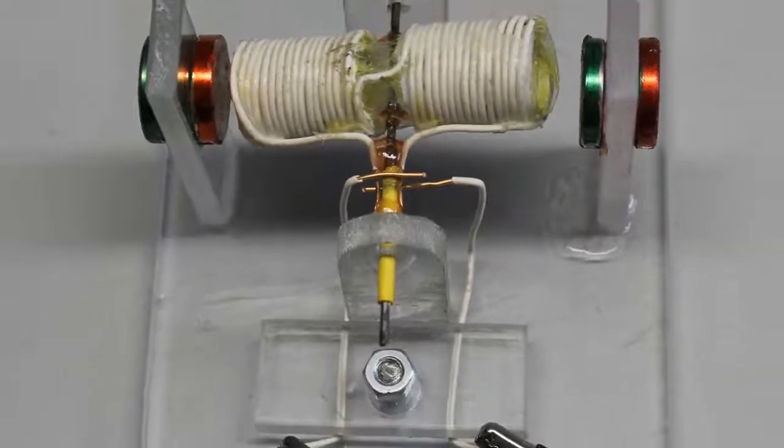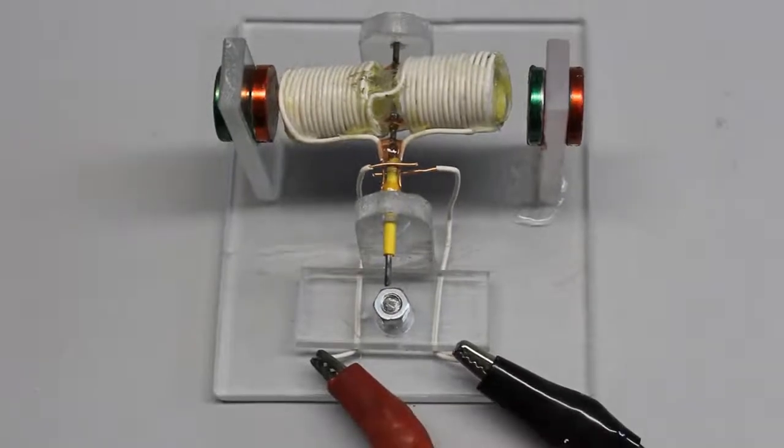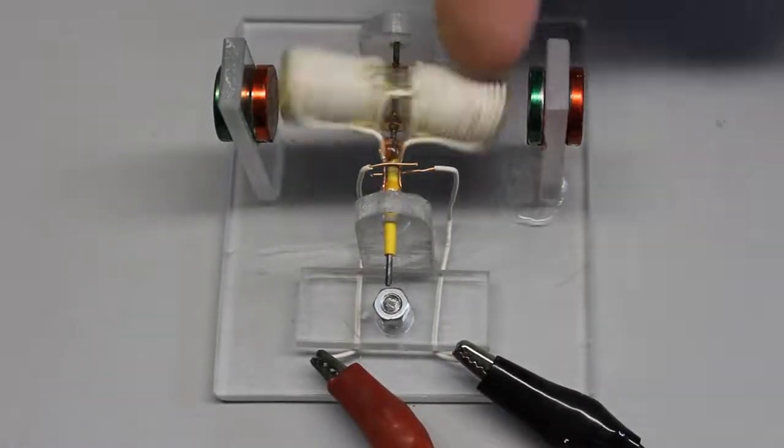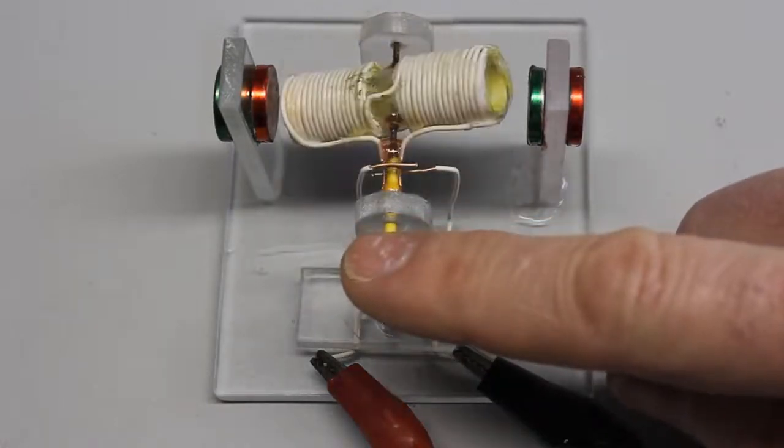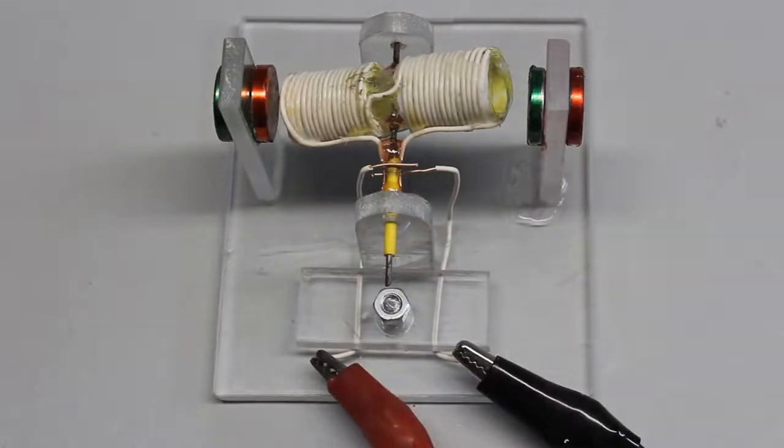The real electric motor also starts spinning after pushing it slightly to make a first contact with the commutator. That need for an initial push is a disadvantage of that simple motor. Another one is that the motor stops spinning when being under load as soon as the commutator breaks the current through the electromagnet.